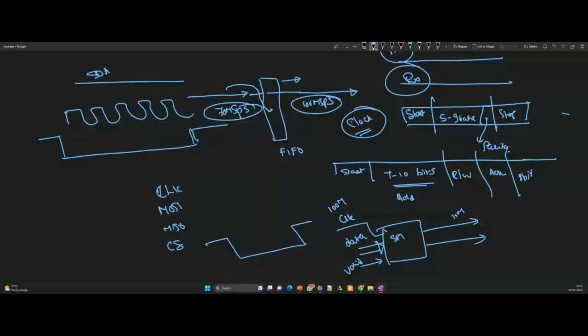So then what's the minimum frequency at which SPI can work? Like also other protocols, what's the minimum frequency that we can use? There is no requirement of a minimum. It can operate at 1 hertz also. But the lower the frequency, it will be very slow, right? There is a limit for higher frequency. Always, you'll have a limit for the higher frequency. Lower, nobody asks. You can operate at 1 hertz also. Nobody bothers. But is it okay for you? That is the question actually. That will be very slow, right? For lower frequency there is no cap, but for higher frequency there will be a cap.